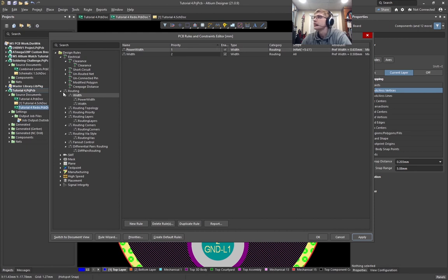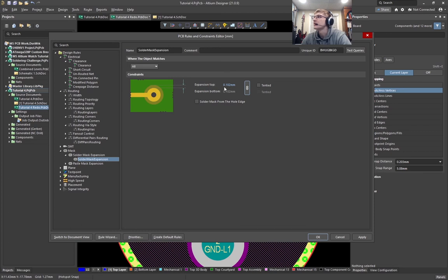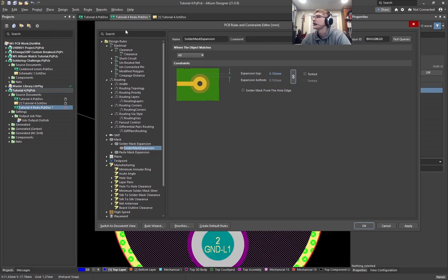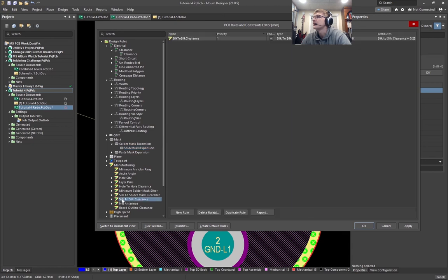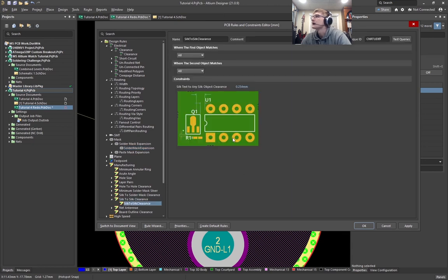So there's a lot of these. You should go through and look at them. You can use the JLC website as a rough guide of what you should be saying for most of these things. A couple I want to look at: solder mask expansion is going to come up later. You'll see numbers for that on the JLC website or whatever manufacturer you use. I want to look at manufacturing. This error right here is actually a silk to silk clearance, i.e. a silkscreen to silkscreen clearance error. So right now we're requiring that there is 0.254 millimeters of space between silkscreen elements. And that's actually not a bad number.